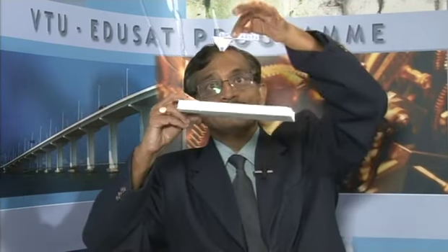Find total pressure on the plate. Again the water level is somewhere at 1.5 meter, same thing, okay? Earlier it was like this, now it's like this, correct? That is the reason I have given a note here, same plate now horizontally immersed. No need to worry, it's again a simple problem. Gamma W, which is the specific weight of water, my dear students, you know the value is 1000 into 9.81, the value is 9810. Area of rectangular plate, A, 4 into 1, 4 meter square.